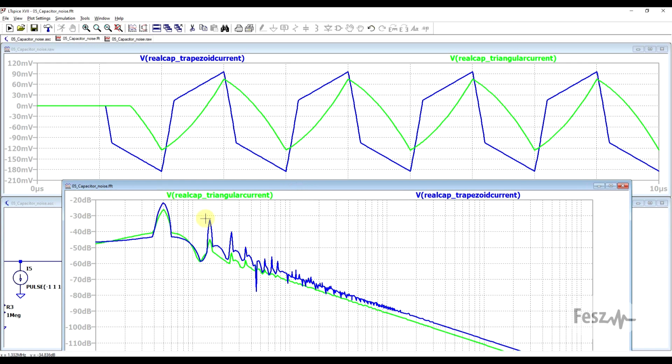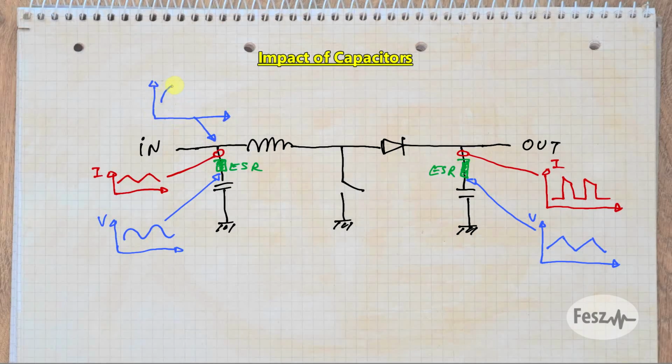than the fundamental, they also contain a bunch of harmonics, and the one corresponding to our trapezoid current has larger harmonics than the one corresponding to the triangular current. So even if the ideal capacitor has some nice looking voltage waveforms, the addition of the ESR ruins this and makes a far more noisy looking waveform both on the input and the output.